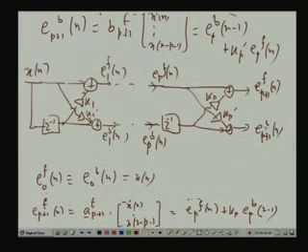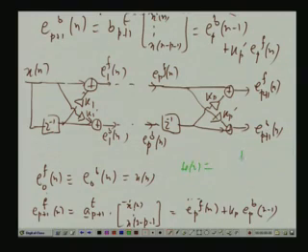So it just shows how the AR modeling problem is related with linear prediction and lattice filters and all that. Only thing that I have so far not shown, and I should show in maybe 5 or 10 minutes in the next class, is that when you solve the Yule-Walker equations, you get a set of coefficients ap1, ap2, up to app. You put them back in the transfer function for 1 over A(z). So you get a transfer function something like this, 1 over A(z), this is that AR model transfer function.